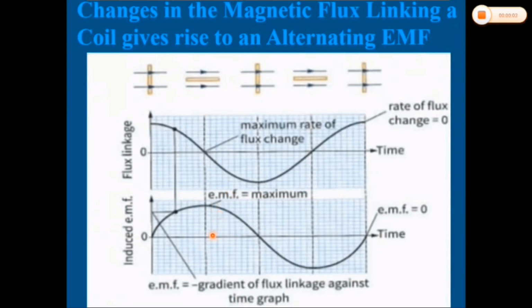And so we can see that for a coil like this, we get a varying EMF. This is how alternating current is generated. In practice, sometimes it's simpler to keep the large coil fixed and spin an electromagnet inside. Now in the next slide, we will discuss an example, and we will also see how we can increase the size of the peak EMF.